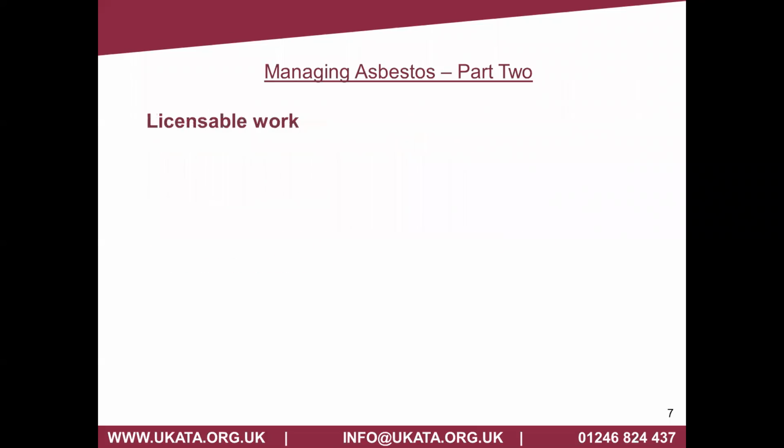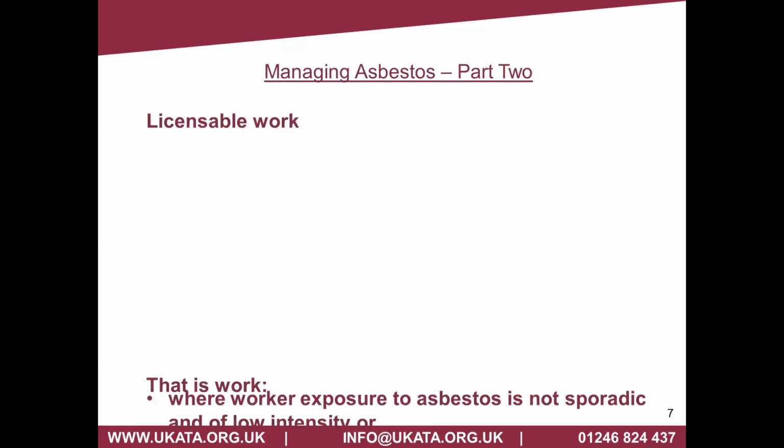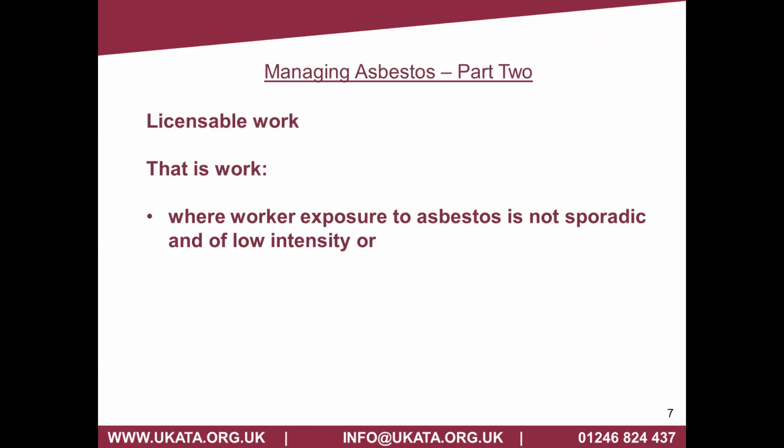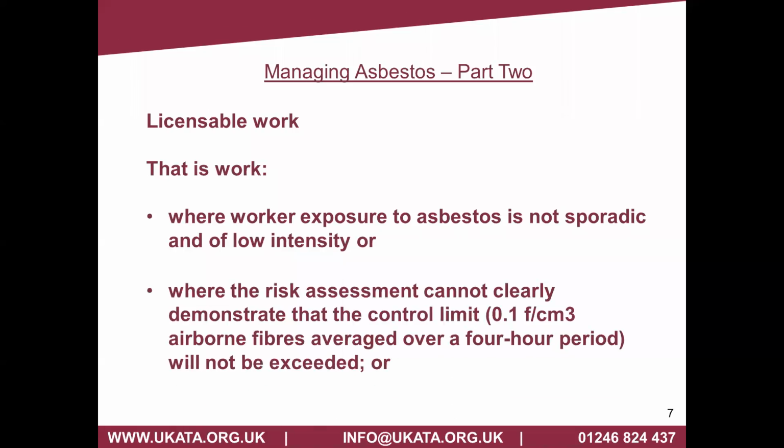So licensable works: when does work with asbestos become licensable, in the sense that you would need to use an HSE licensed asbestos contractor? That is defined as where the exposure to the individual or the work is not sporadic and low intensity. What that refers to is low risk, or low levels of exposure over a period of time. Now, the current figure for that is 0.6 fibres per centimetre cubed over a 10-minute period. Obviously, most work activities are going to lead to longer than 10 minutes on site.